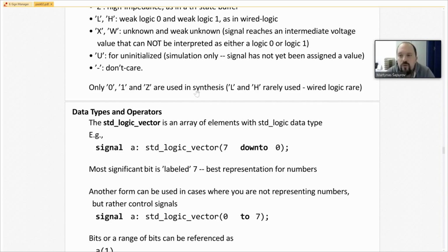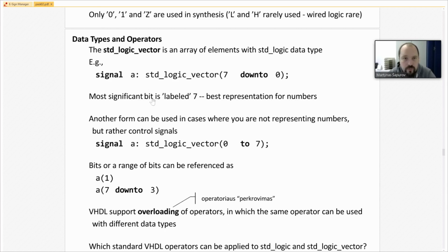If you remember the theory of MOSFETs, the gate is completely insulated from other parts. This means that it has an input impedance of several megaohms. So this means it will get the high impedance state. So we reconnect, instead of connecting the drain, to connecting the gate.